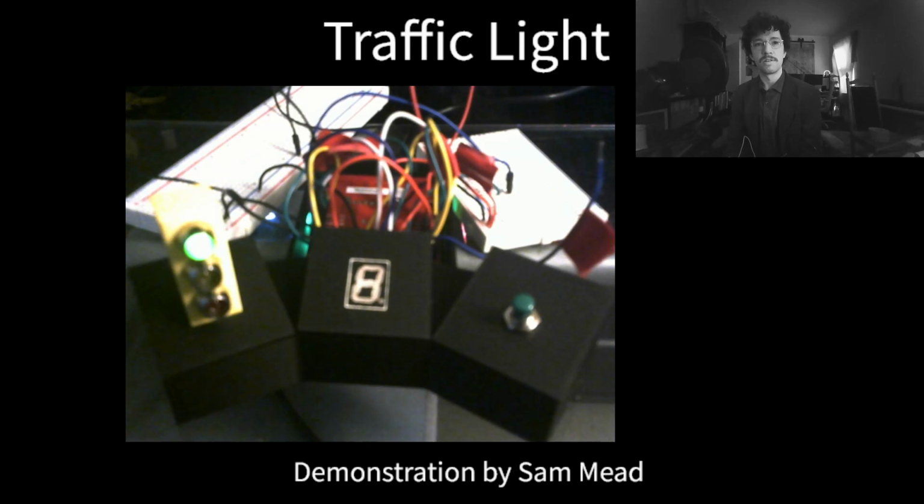First, let's take a look at what happens if the pedestrian does not initiate a walk sequence. If that happens, then we just cycle through the natural sequence, which would be 30 seconds of green, 10 seconds of yellow, and 10 seconds of red. And these, as I mentioned, are essentially states. So we have a green state, a yellow state, and a red state. That order will never change regardless of input or no input.